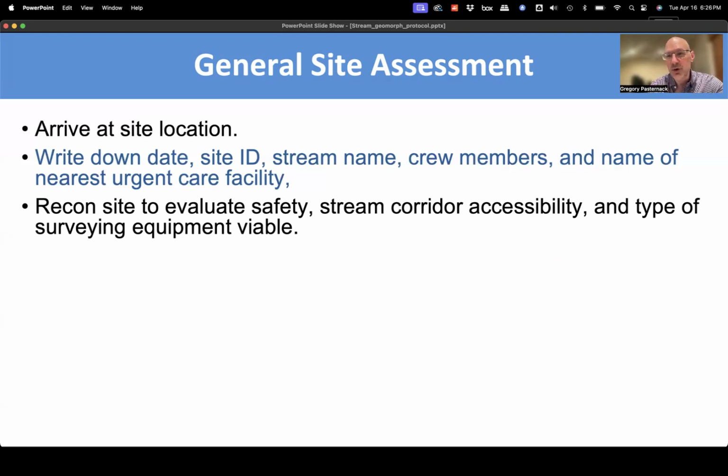If the sky is more open, and I'll talk a little bit more about this later, then the RTK GPS will be the easiest and fastest if you have a clear view of the satellites, and preferably if you have cellular connection. And the only time you're going to use the total station is if you have pretty good visibility over a good distance.